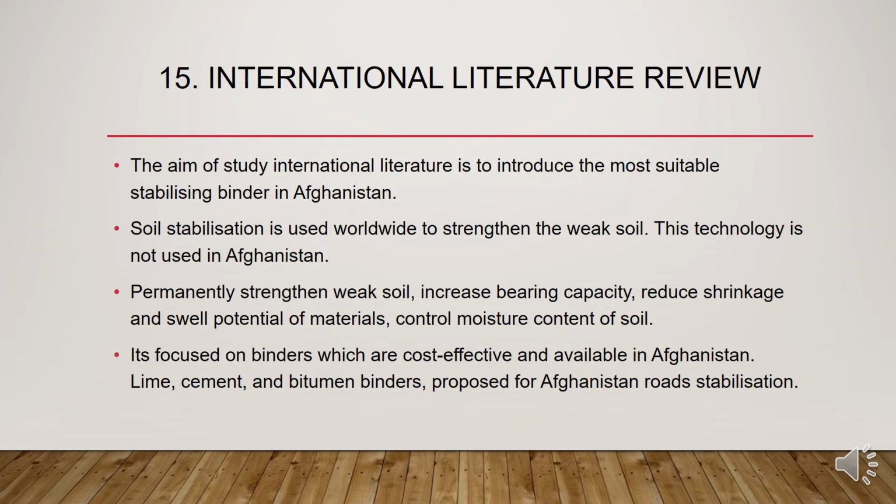In this literature review, the focus is on binders which are cost effective, friendly with the environment of Afghanistan, and easily available in the markets. Therefore, lime, cement and bitumen binders are proposed for Afghanistan road stabilizations, which are mostly available in the market and nearby countries.